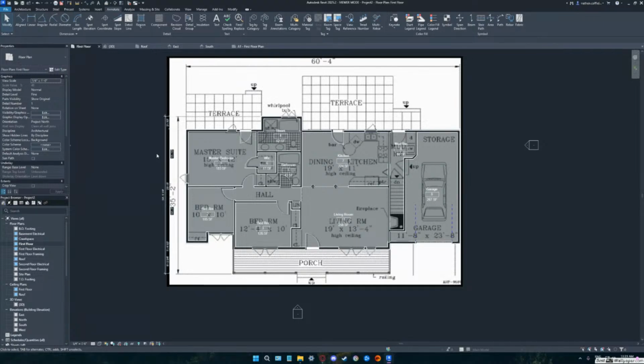Or when you come time to dimensioning, you just want to make sure that the only thing that's turned on in the view is dimensions, walls, doors, and windows, and then go do your dimensioning. But as I said, most people, beginner mistake, I'll come to their file and they're like, Brian, why can't I do that neat little activate dimension? And it's because instead of dimensioning to the walls, they were dimensioning to that piece of closet shelf. Because when you put the closet shelf in there, that's how it works.